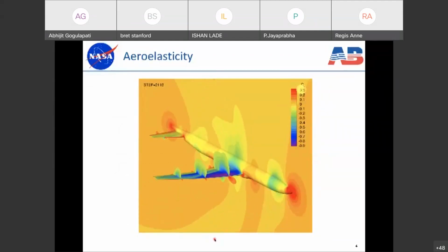And if the dynamic pressures are relatively low, which means we're flying relatively slowly and/or at relatively high altitudes, then those two disciplines will settle into an equilibrium. They'll settle into a static aeroelastic equilibrium state. But if we're flying at relatively high dynamic pressures, say low altitudes or very high speeds, then they may not settle into an equilibrium, which is shown in this video here.